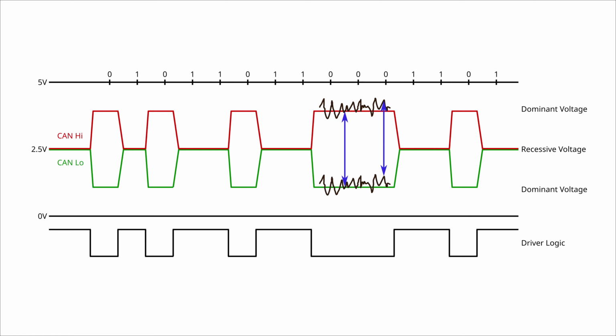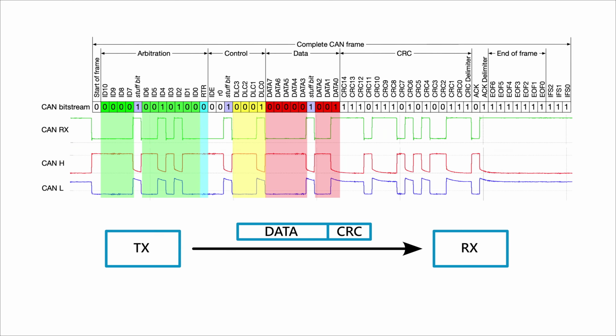What should we do if data has been damaged? Don't worry, CAN bus has its own error detection mechanism. This implies that the transmitter will calculate CRC based on the sent data. This will be sent out along with the data. At this point, the receiver will recalculate the received data's CRC. It checks if the received CRC matches the calculation. Data is discarded if they don't match. That's how the process works.